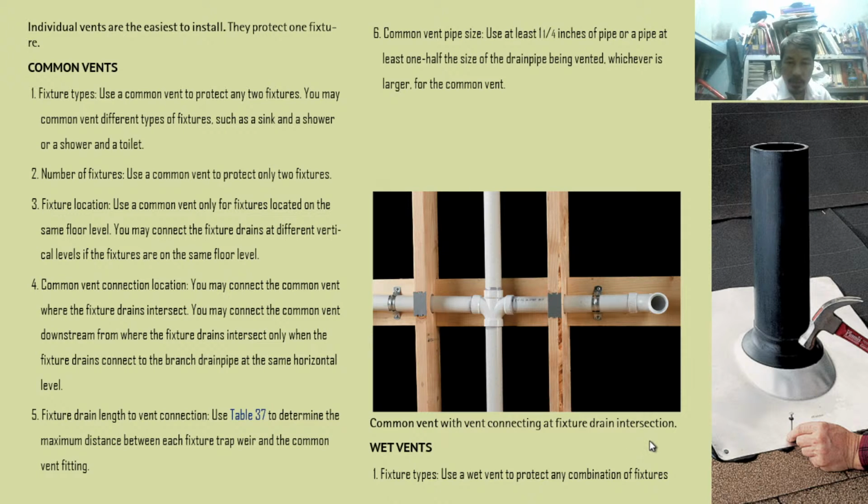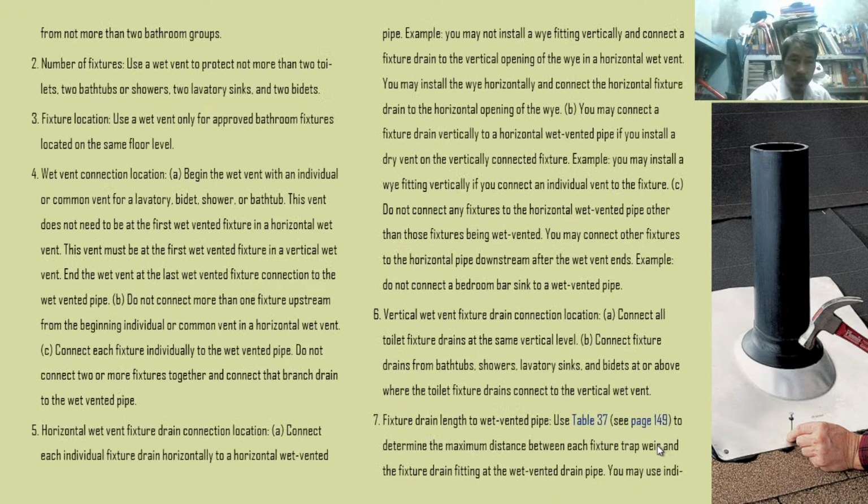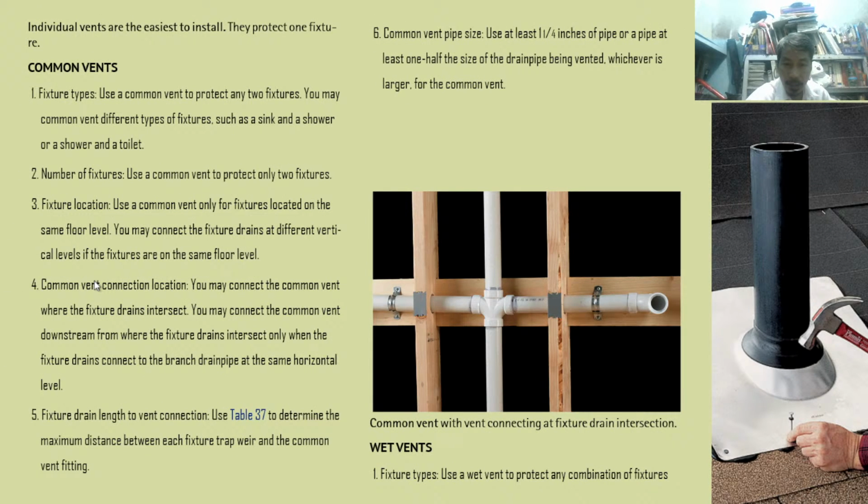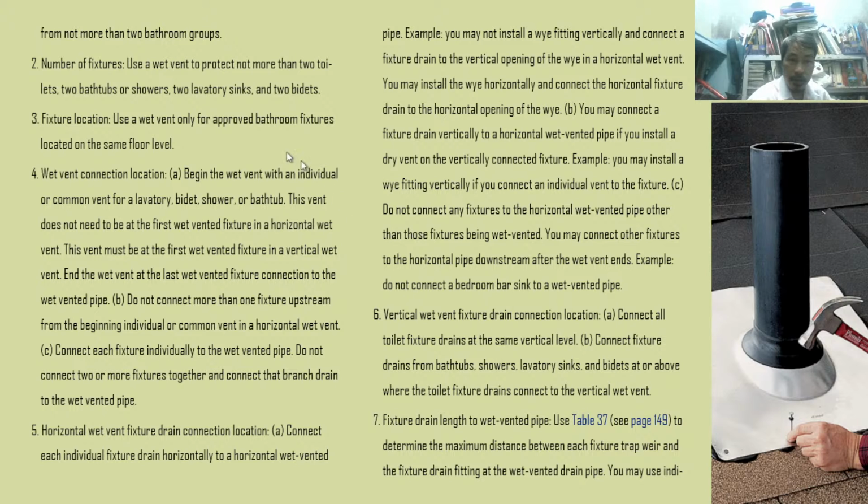Wet vents. How about using wet vents? Use a wet vent to protect any combination of fixtures from not more than two bathroom groups. Not more than two bathroom groups. Any combination of fixtures. So you can use wet vents.